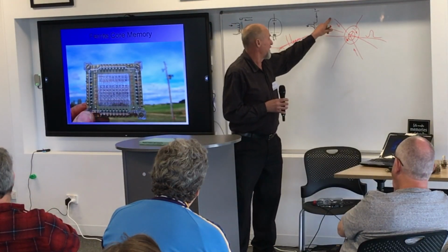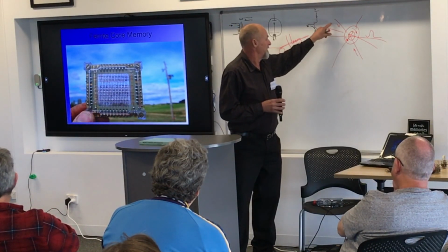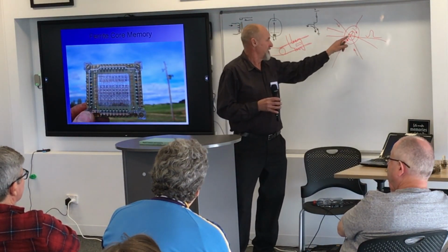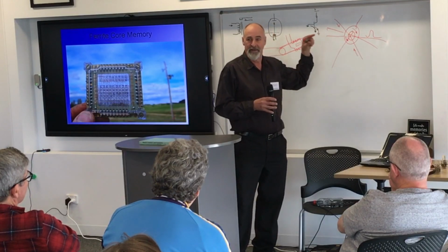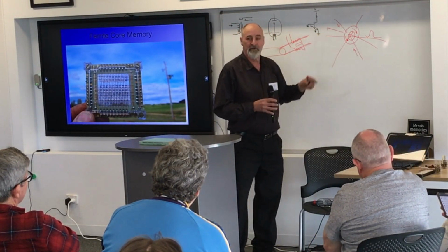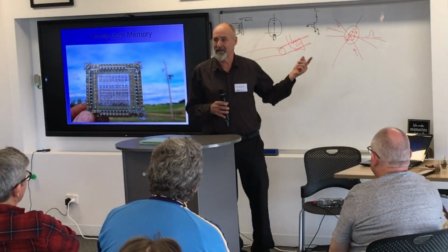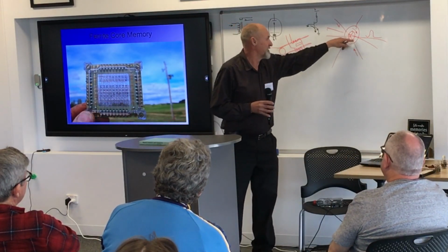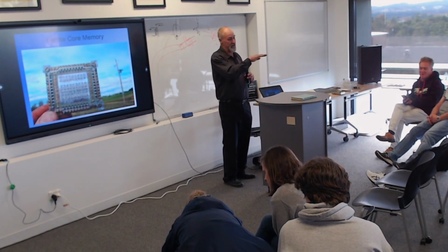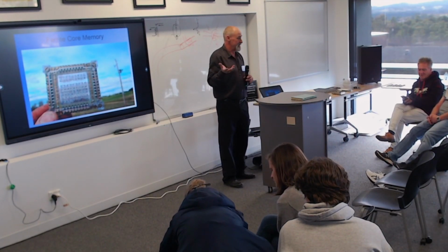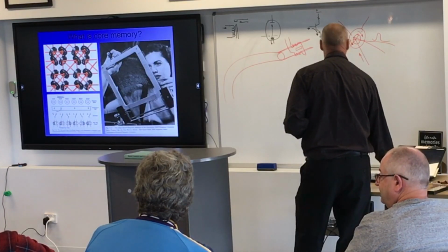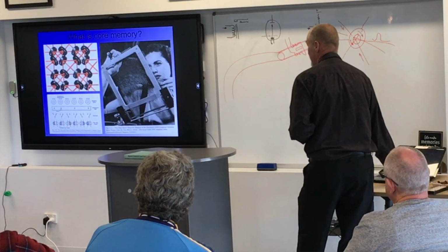What it does is it biases one of these lines. It puts a current bias on the sum of the currents through the bead, so that one plus that one minus that one equals not enough to change the magnetic field in the ferrite, so it can't be read. Then they stack them and have separate inhibit lines for each layer to give you a 3D memory. So that's a 2D memory device there.